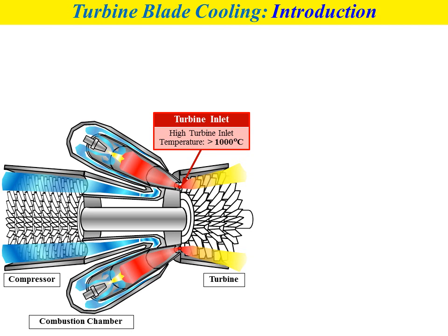Okay, so if we can increase the turbine inlet temperature as high as possible, we will have several benefits. First, in terms of economy, the specific fuel consumption will be reduced, which means we will use less fuel but have a high value of efficiency.